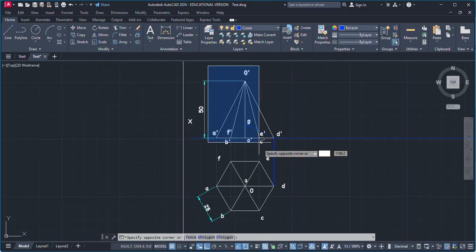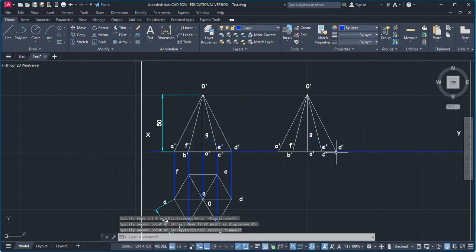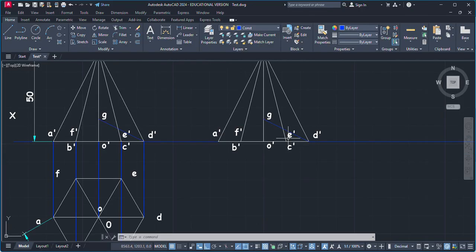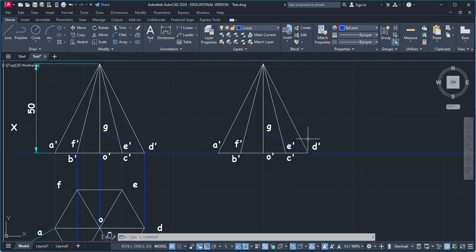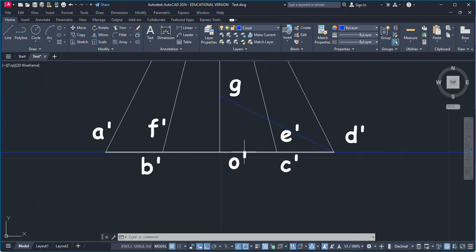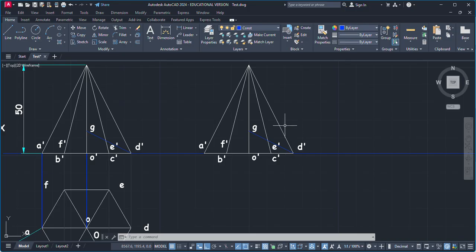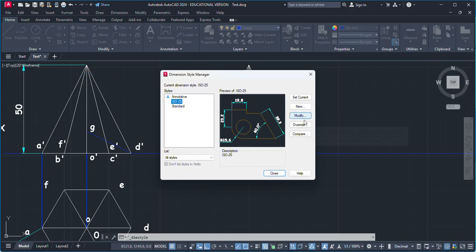Simply just select this thing. Now make a copy of it first. Now rotate it in such a way that this line, which right now, this D dash G, is inclined at some angle with HP, after rotation it should become vertical to this reference line. Okay, so the simplest thing to do is just measure the angle between these two. Okay, to perfectly make this thing vertical, from the format I'm just going to change the angular precision.